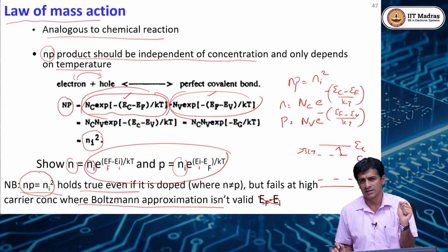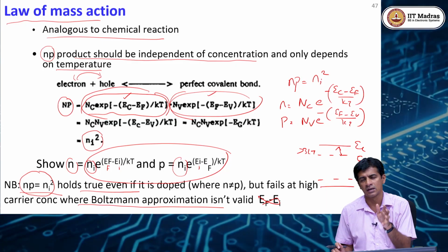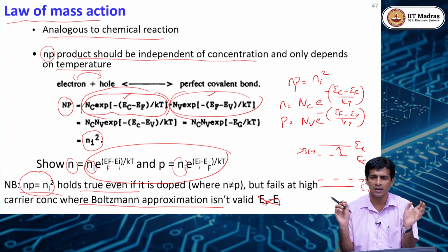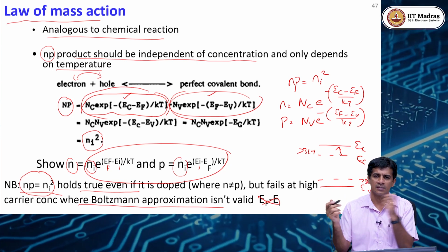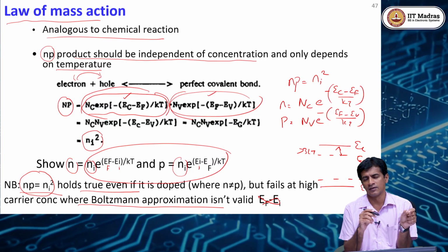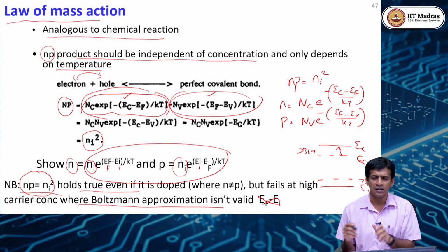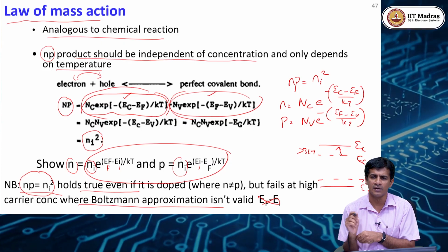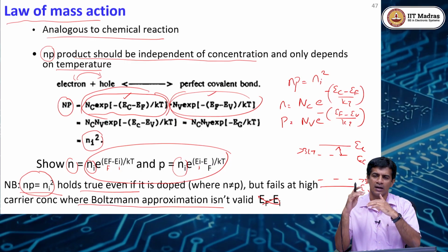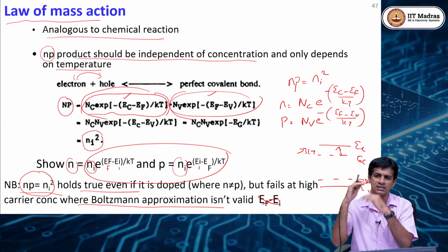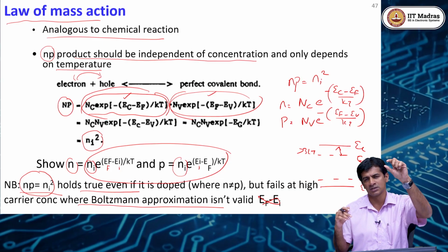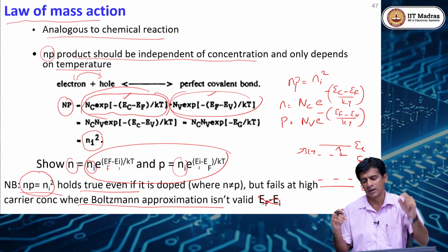Then we saw the effective mass approximation. The effective mass approximation allows an electrical engineer to do all the device analysis without knowing anything about quantum mechanics, because all the information about the quantum mechanics and the periodic potential is encoded into the effective mass. The price we have to pay is that you need to use a different effective mass for different materials. Then we discussed the Fermi level. The Fermi level lies at the topmost occupied state for metals. But for materials with discrete energy bands, at 0 Kelvin it lies exactly between the topmost occupied level and the bottommost unoccupied level.